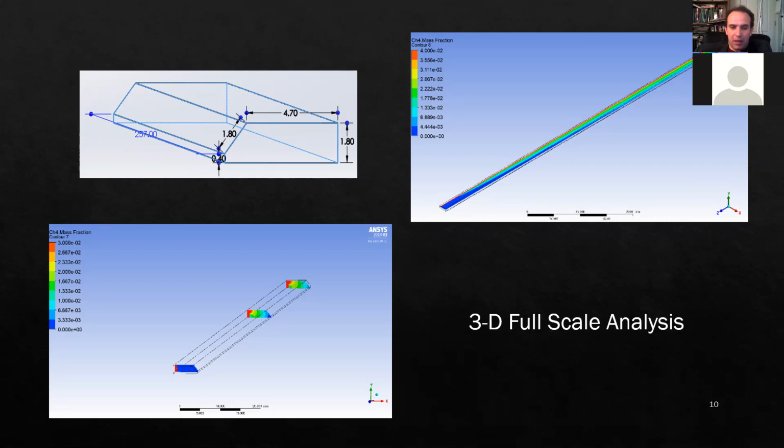At the time, I turned off all other species and I just defined at these boundaries along the face, I set it to be 1, which would just be full, just CH4. And that's when I realized, I better go back and check to make sure that these chemical interactions or concentrations are actually correct. And it appears that I had things set correctly.